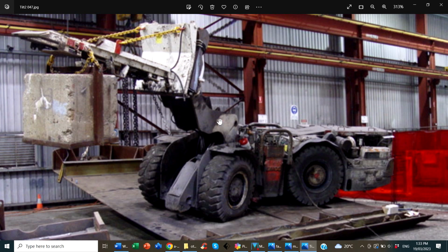One of the issues with tilting articulated vehicles in their steered condition is you need to be very careful that the load doesn't get on the wrong side of the axis of the tilt table. I've had a couple of occasions using tilt tables where I was concerned that the whole thing, not just the vehicle and the table were going to tip. So you need to be careful of that.